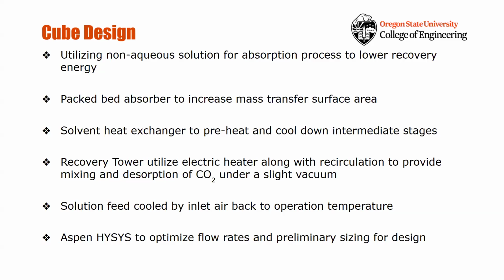And the recovery tower will use an electric heater along with recirculation to provide mixing, and it'll be under a slight vacuum to help CO2 desorption. Our solution will be cooled by either inlet air or other cooling devices, which is up in decision right now. And we will be using Aspen HYSYS to optimize flow rates and preliminary design sizings for our overall design.